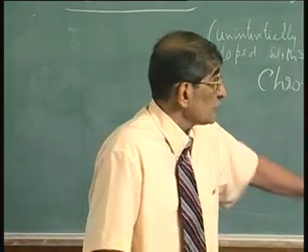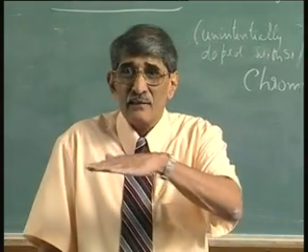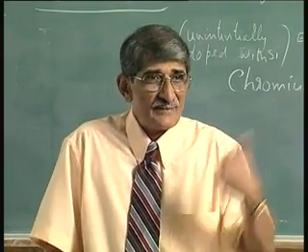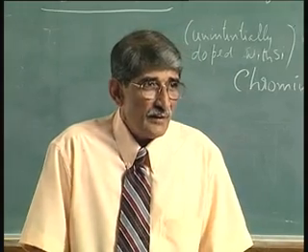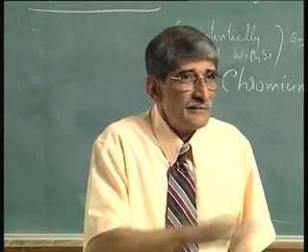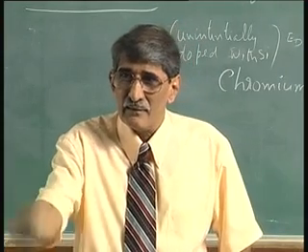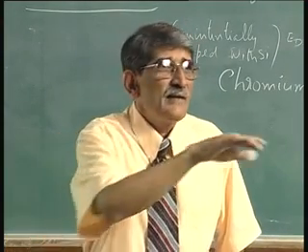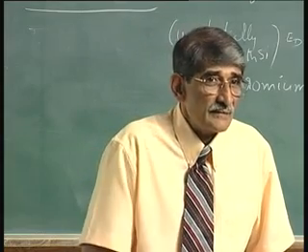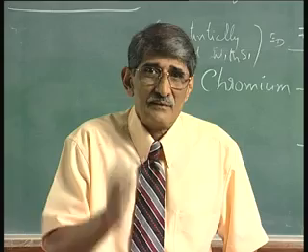It introduces a deep level at the center of the forbidden gap, that will compensate if it is n type. Whatever gold you add, beyond that point it will become intrinsic. They were selling like that, but once you use that wafer for making devices, disaster.